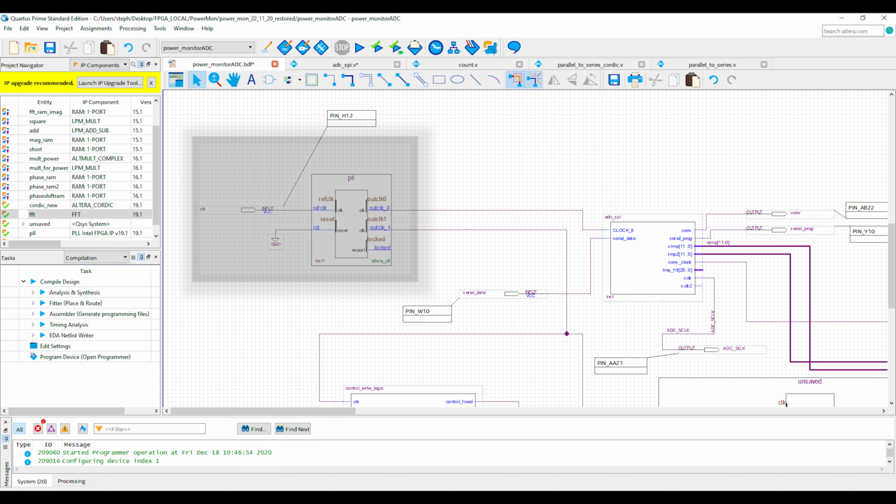This contains the interface code for my ADC converter, and the chip we're using is the LTC2308, and this runs off SPI interface code. So the starting point really is to look at the timing diagram.